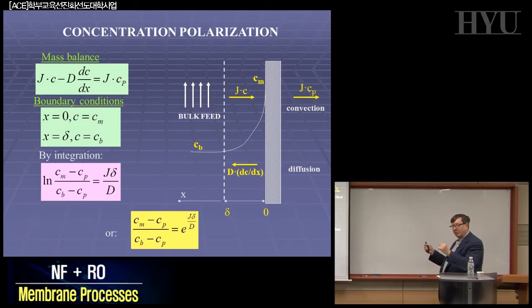Not at all. The membrane was perfectly working, but it's not working against CB. It's working against CM. And CM was no more 0.5 molar, it was now maybe 3 molar. If you make the calculation again, you'll see that the concentration downstream is exactly appropriate. So apparently you have a broken membrane, but it's a question of fluid dynamics.